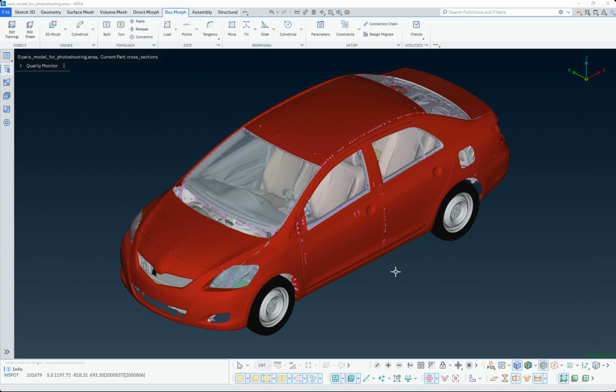To isolate specific regions of the model and streamline selection operations, the Feature Selection toolbar is activated. This toolbar consists of four major groups. First, Entity, where nodes, entities, entities from nodes, or nodes from entities can be selected. The Nodes from Entities option selects nodes by hovering on entities, while the Entities from Nodes option selects entities by hovering on nodes. A red indicator appears on the Ent icon in order to help the user understand that this is not the default configuration of the function.